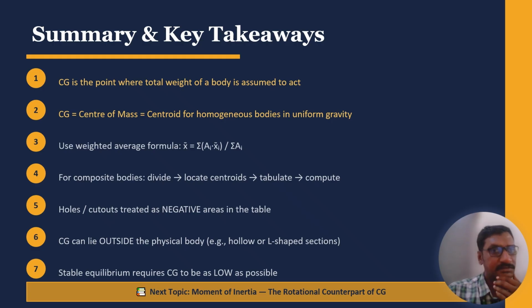The next takeaway is that stability requires a low center of gravity. In engineering design, as you understood in the previous set of applications, stability against tipping, rolling, and capsizing requires the center of gravity to be as low as possible. So if the center of gravity is high, it is a problem. This principle governs the design of vehicles, ships, structures and different equipment. The lower the center of gravity relative to the support base, the more stable the system. This is why heavy machinery is always built with heavier components at the base.